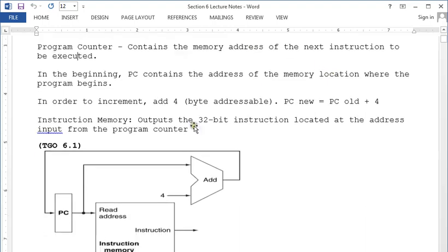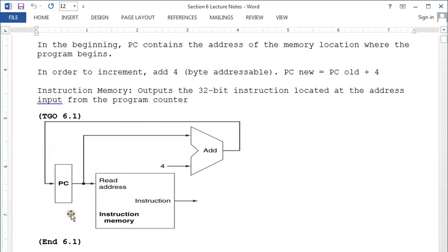So this stage is simple. Program counter, we have a value, goes into the instruction memory. We have the read address, we take that PC, we have an adder here. We show in the problem how you're going to do that differently in your VHDL assignment. But in this case, we have a 32-bit value, and this should be 100 with sign extended to 32 bits. And then you have an output. Now, unfortunately, it's not going to be as simple as this because we have to calculate branch and jump addresses. But this is just the first stage. So now we have our 32-bit value out here.